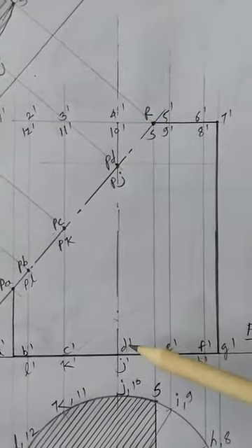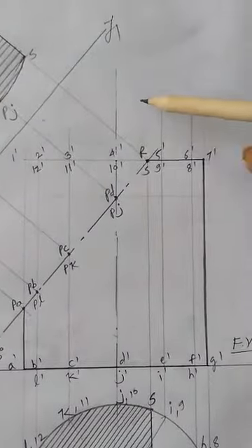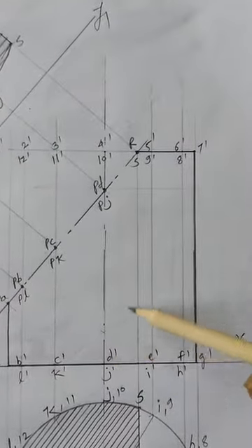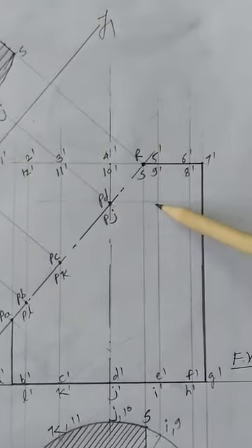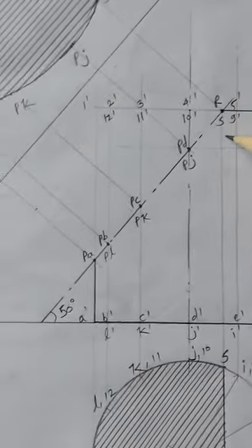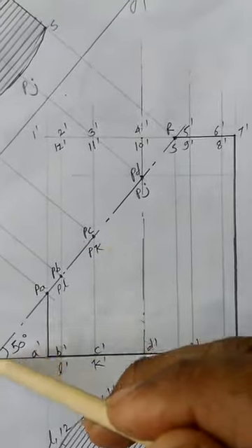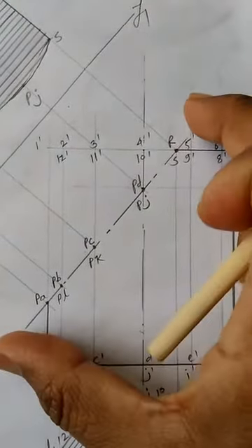But as per the mentioned narration only we have to proceed. So that 65 mm distance I have marked here. Using a construction line, placing the protractor and marking the same angle of inclination, that is 50 degrees, I have shown the cutting plane.